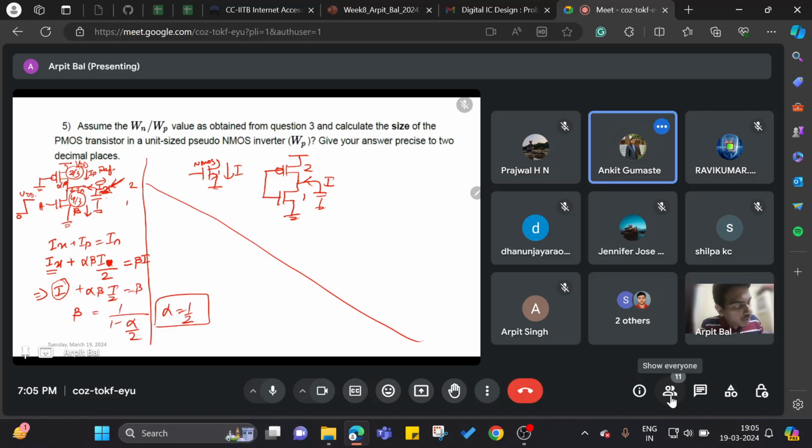And what we are actually concerned about is the load current. So the load current of the design under test should be same as the load current of the reference inverter. And because in this case we started with this consideration that my load current is equal to I, and after that I figured out the sizing of 2 by 3 and 4 by 3. So because of this reason, whenever I'm considering the pull down network, I'll take this as the reference inverter. Okay, so got it.